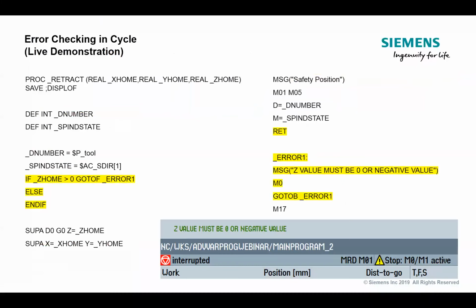So what we're doing here now is I'm not adding any more variables, but I'm saying, hey, maybe on this machine or these series of machines, I know that all machine travel is a negative direction, right? It's pretty common in Z that if I move the Z in a full plus direction, where it stops is machine reference 0, right? So that means prior to setting a work coordinate, all travel in Z is negative. Well, since I know this value is based on the machine coordinate system, then it stands to reason that I want to make sure that I don't plug a positive number in, at least for Z.